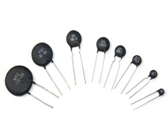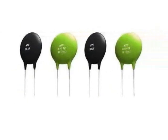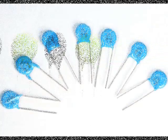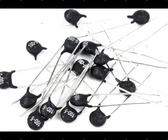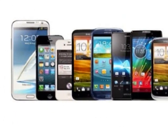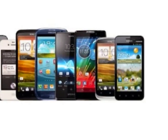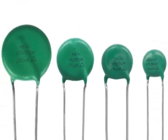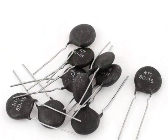These resistors are used in protective circuits etc. in order to regulate the load current during overheating. The value of NTC resistance is linear in the specified range in degrees Celsius and starts to become nonlinear with increasing temperature. In smartphones, the function of NTC is to report the battery temperature to the phone. During charging, if the battery temperature exceeds the allowed limit, the phone will immediately issue an order to stop the charging operation.